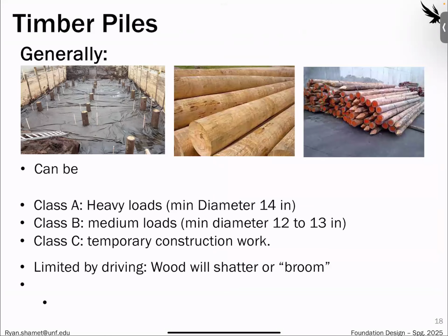All right, the last few we're going to go through quickly just because we don't have too much detail on them, but these are still used. Boardwalks and everything, timber piles are used also in ground improvement. So these are just generally the cheapest, most like private work. You're not going to use these for DOT or any large federal projects.